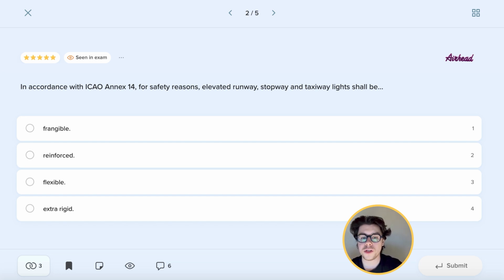All of the location signs, lights, and also everything past the aerodrome in the extended center line and clearway needs to be frangible. I'm sure you've heard of the Jeju accident where the aircraft has hit a concrete wall, and this is the exact reason why all the signs and all the buildings around the airport need to be frangible and properly marked.